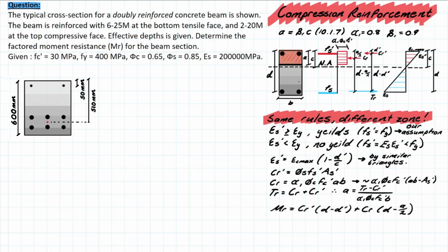And the main takeaway for compressive steel is that it's going to be improving the moment resistance of your beam because you're now considering an additional contribution from this steel in the compression zone without over reinforcing your beam. You're still going to be in that steel controlled failure where we are going to have that slow kind of failure mode instead of the sudden concrete failure. So that's the main takeaway and why we need to do compression reinforcement sometimes.